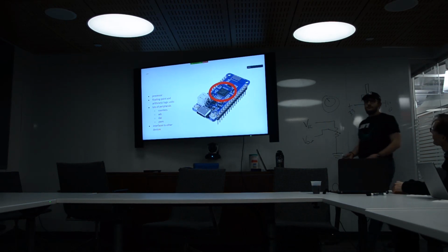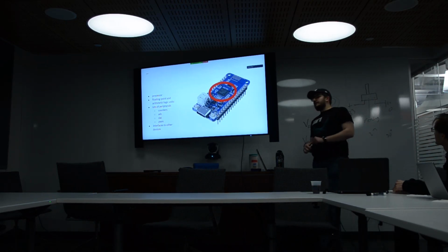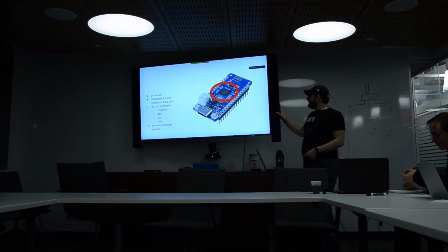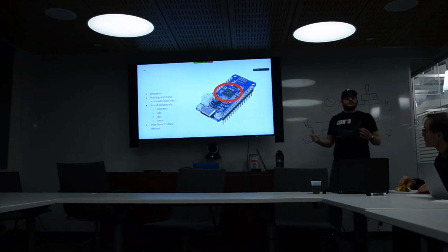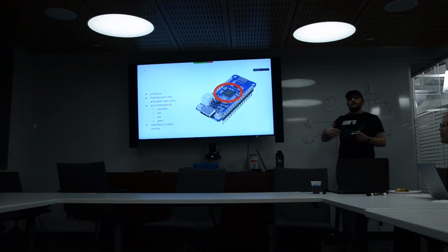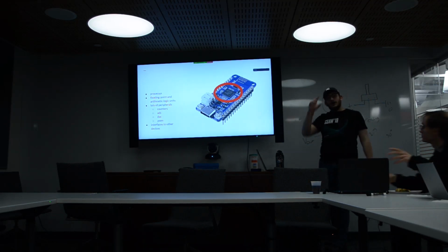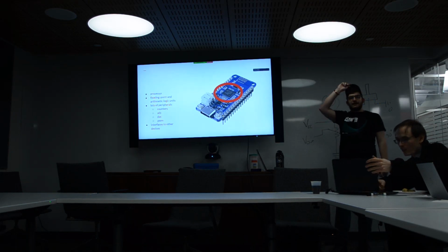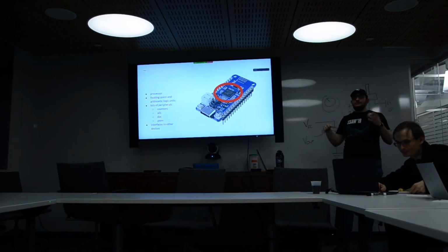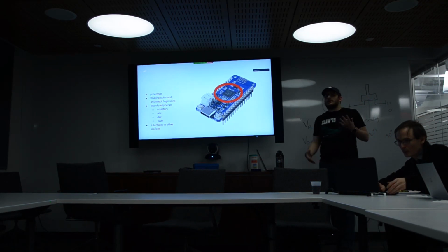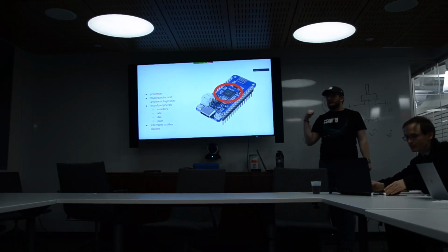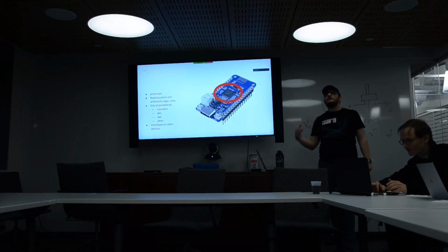On the flip side of that, you have something called a digital to analog converter and something called PWM. PWM is pulse width modulation, which is just a way of getting a voltage different from the one that you have. It's crappy, but it can also be used to control a bunch of things. And a digital to analog converter is a much cleaner way of getting a precise voltage.